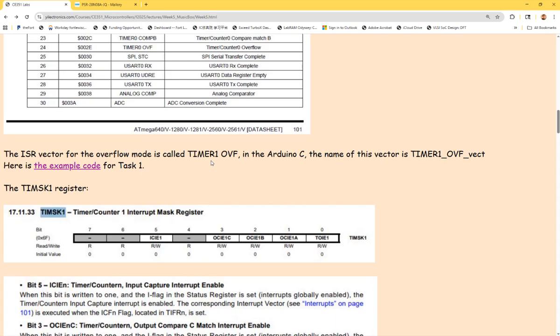It just keeps going like this, and whenever the timer, which is running behind the scenes, overflows, it interrupts. So it could happen in the middle of the loop function, and it interrupts and goes to the ISR and runs whatever is in there, and then it will come back to the same location and keep running the rest of the code. That's how that works.